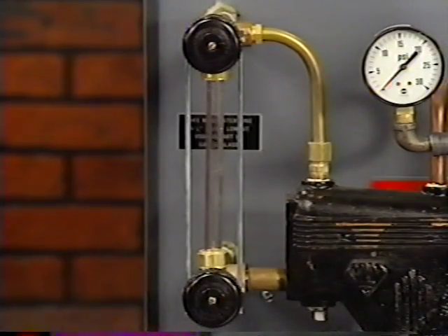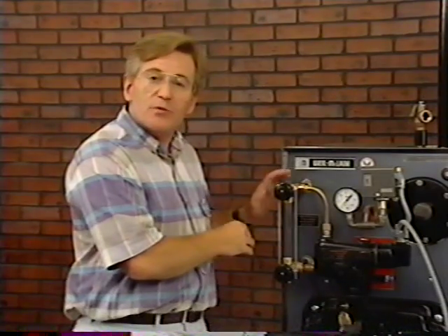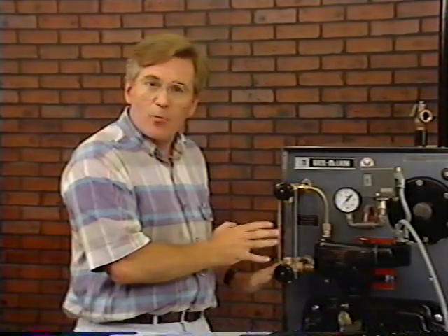All steam boilers provide for visual observation of water level in the boiler with an externally installed water column gauge glass assembly. This gauge glass is mounted to the boiler through tappings so that you can see the operating level of the water within, providing for a visual inspection against running the boiler with too little or too much water.